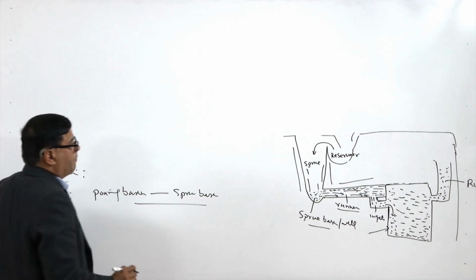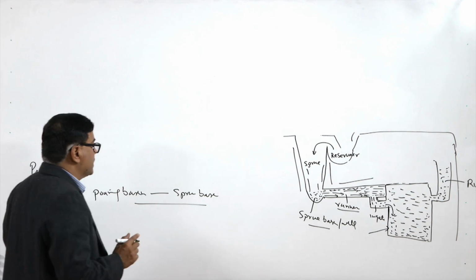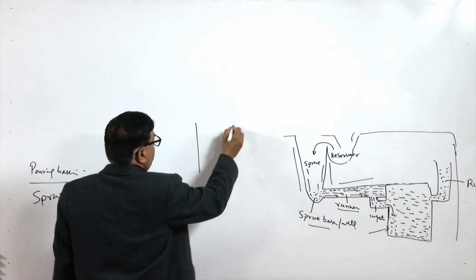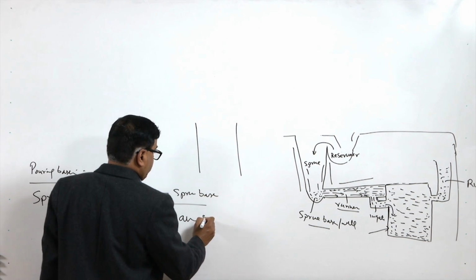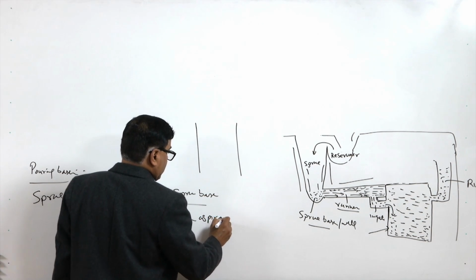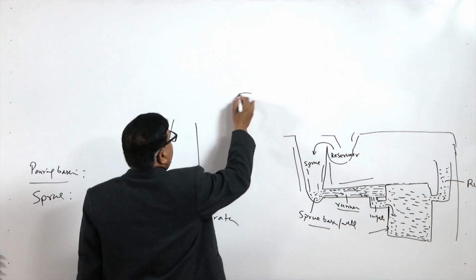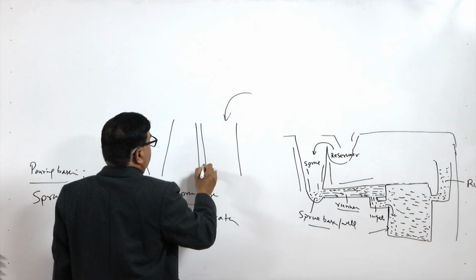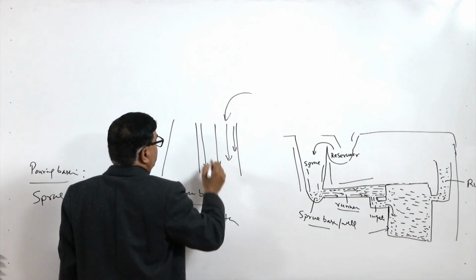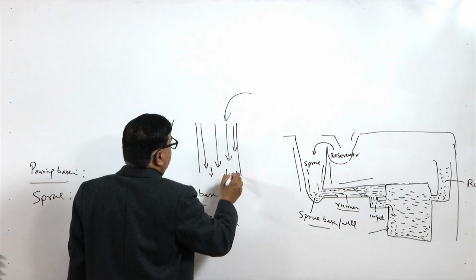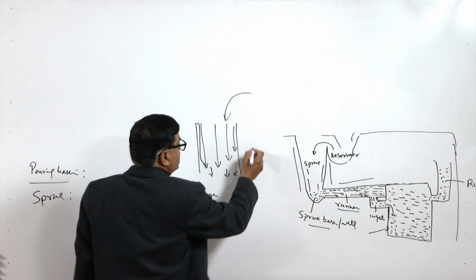A proper design of the sprue is needed, because a simple cylindrical sprue promotes air aspiration as compared to the tapered sprue. We know that if the molten metal is fed from the top, with the change in position, the velocity increases as the molten metal moves down, and because of this, the separation of the molten metal from the walls starts.